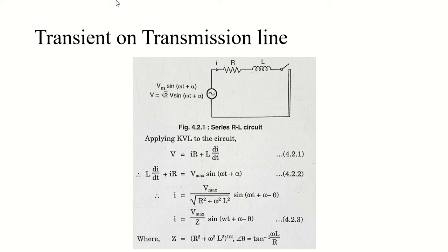So the short circuit currents are estimated by analyzing symmetrical faults. Though these faults are very rare, you won't find symmetrical faults occurring very often, but symmetrical faults lead to the most severe fault current, and because of that your system can suffer severe damage, so it must be stopped.